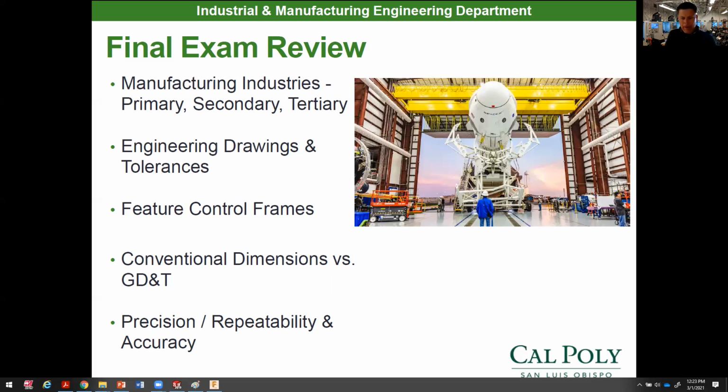So I would know about the 5 different categories of GD&T tolerances. If you remember, that was the form, the profile, the location, the orientation, and the runout. Well, within those 5 categories of GD&T tolerances, we have specific callouts. Now, remember, there was basically 12 or 14 in the old days, but 12 different basically geometric characteristic symbols that you can go ahead and control your parts relationships to other features or datums with. And that's what GD&T is all about, is preventing extreme form variation and being able to communicate your design intent